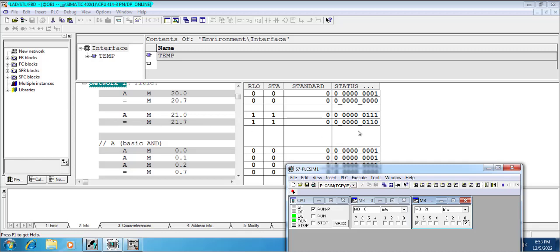Now that the RLO is 1, the assignment instruction comes, moves the value of the RLO to the address 21.7, which is actually stated here. So 1 is moved to 1, and also sets the FC bit and the OR bit back to 0.